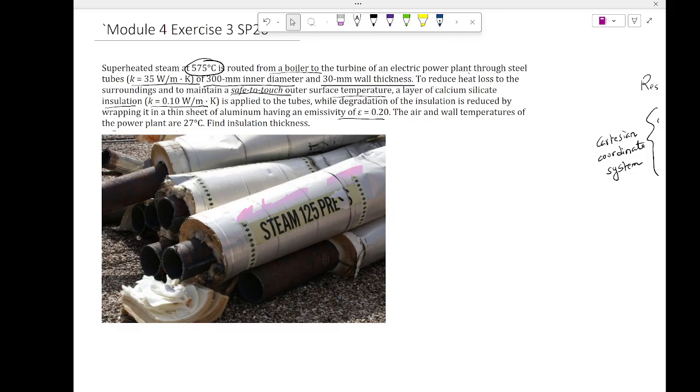Along with this chapter's knowledge, which is obviously we have a cylindrical wall, which has two different materials, which has two different resistors. You just did the resistance equation, right? Everybody, what is the resistance equation? Ln of outside radius over inside radius divided by 2 pi kL. Everybody remember that? All right. So kind of getting a clue how to deal with this problem? No? Yes? All right. Let's do the problem then.